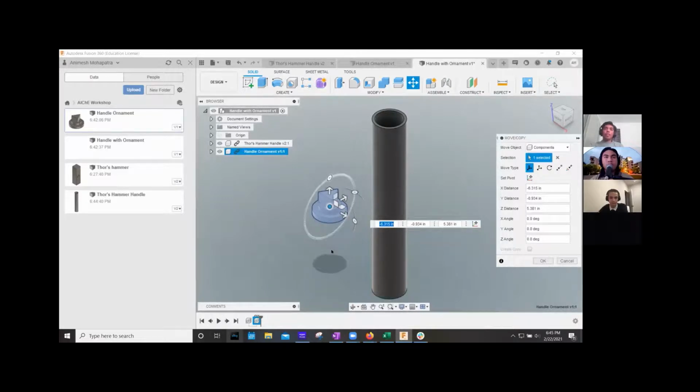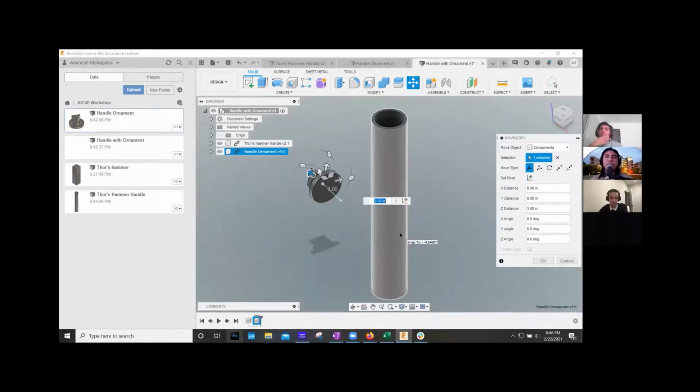You can move it around with this middle part, and you can rotate it in all the different axes. It's kind of fun if you want to just play with it. Oftentimes, if you have a big assembly, you'll put something in your assembly and it'll be at a different corner of your assembly, so you won't know where it is. What you'll have to do is go to your components and then click find component or go to component over here, and then you'll find out where it actually ended up. But we have a small assembly, so we're lucky.